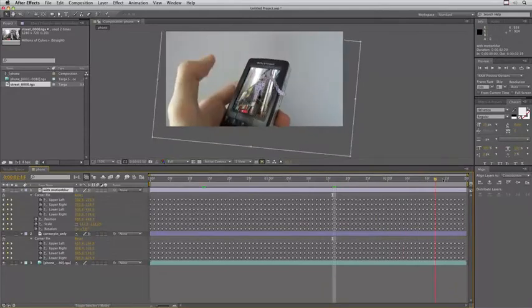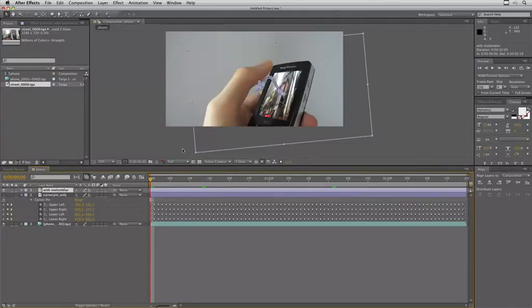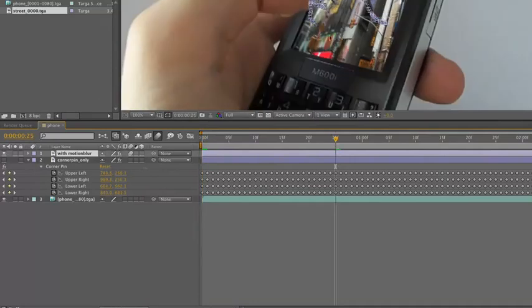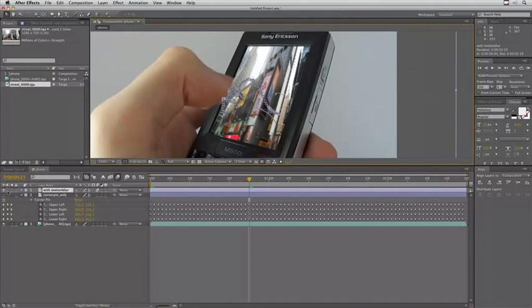The introduction of these three new attributes did not change anything, but if you turn on the motion blur for the layer and the motion blur preview, you can see that the new layer will have motion blur applied to it. The other layer that has only corner pin applied will not be able to use the motion blur because the layer doesn't have the transform data on it.